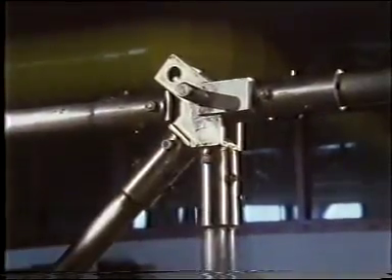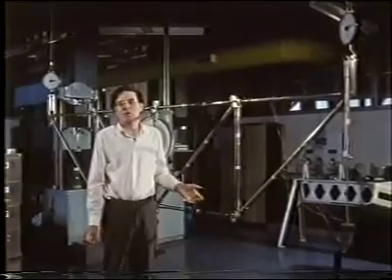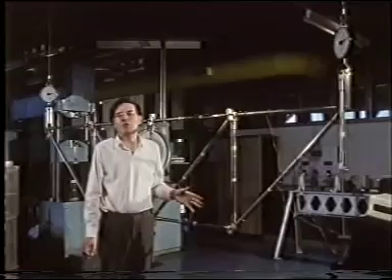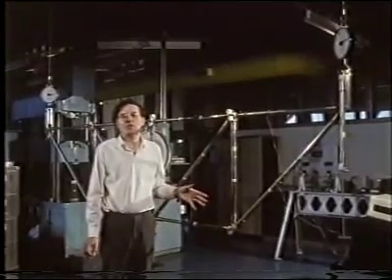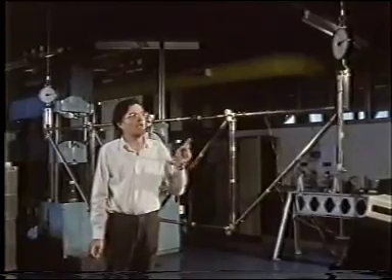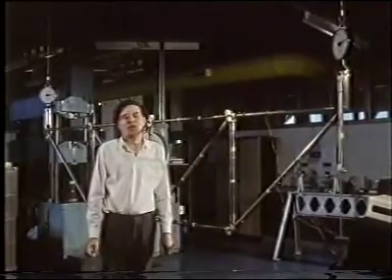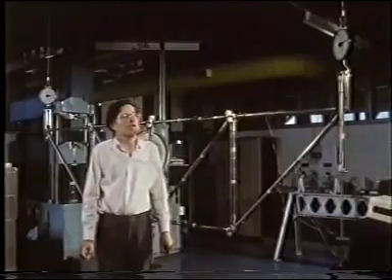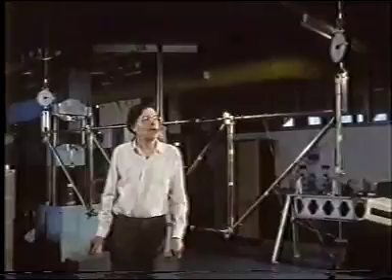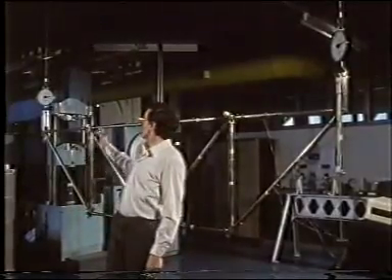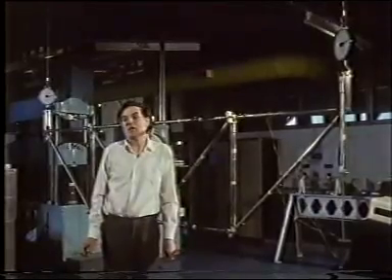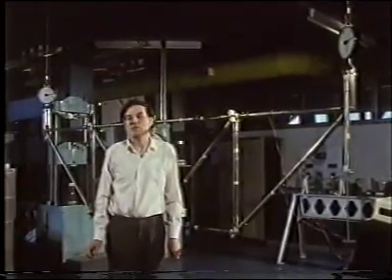The first thing to do is to establish the vertical equilibrium of the structure so that we can find the weight of the structure. Vertical equilibrium states that the total upward force must be balanced by the total downward force. So by reading the spring balances at the end of the structure, I can find the weight. The spring balance at this end reads 120 newtons, and at the other end it reads 120 newtons also. So therefore the total weight of the structure must be 240 newtons.